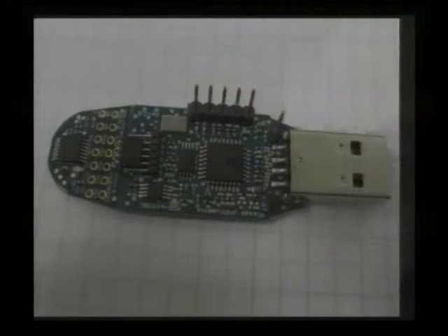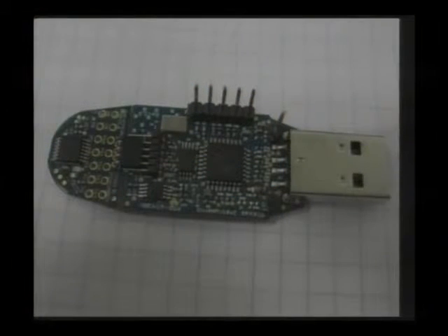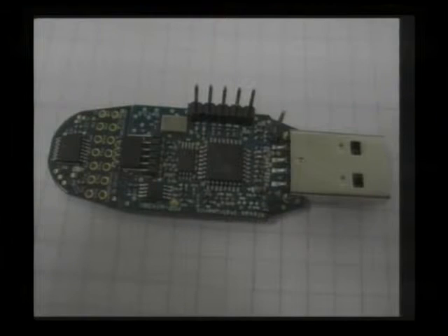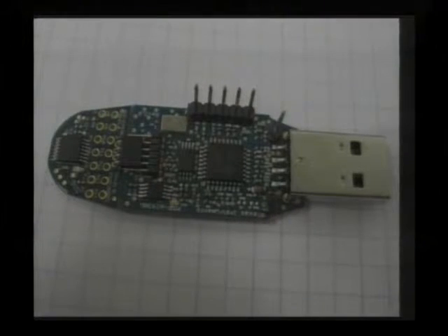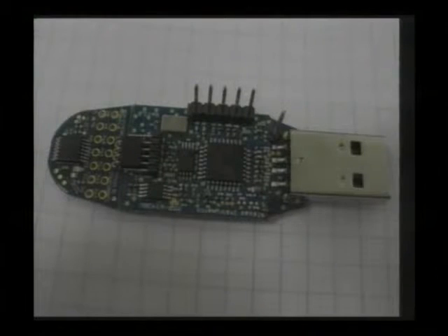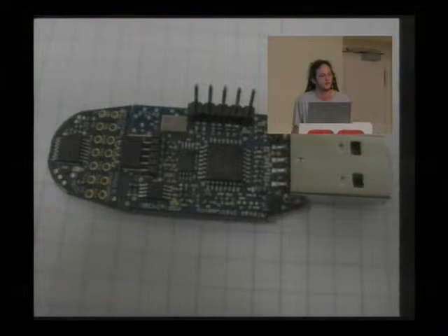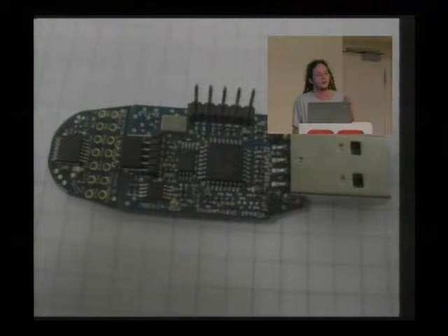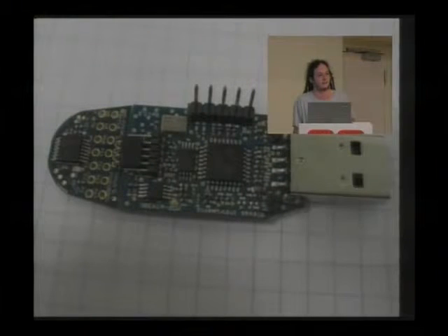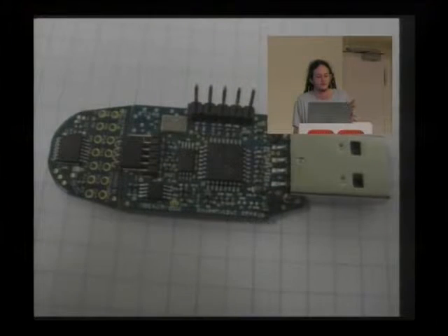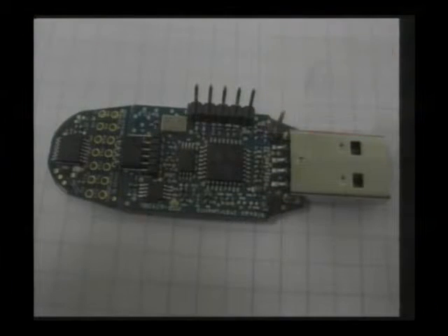This is the device that we'll be hacking. The piece on the left is the target board. It's about the size of a 1 euro cent coin, and it has the MSP430F2012 or 13 on it. There's also an LED and the pull-up resistor and the decoupling capacitor and everything you need to have a functional device. But it's small, and it doesn't have much power. It only has one serial port. It can only do so much.